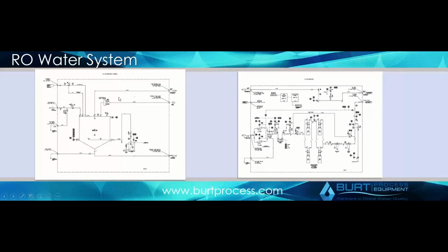water tank. This is your ozonization. This is where you do your sanitization of the system. And then this is your final distribution, which really is a very small portion of your overall system. You have your UV light, resin, final filters, and then coming back here, this is where you have your pressure regulation off of your loop.